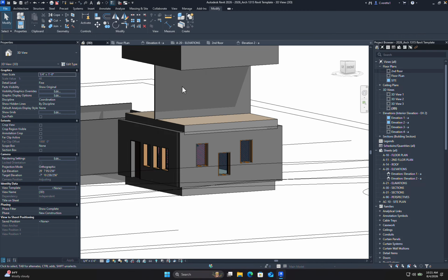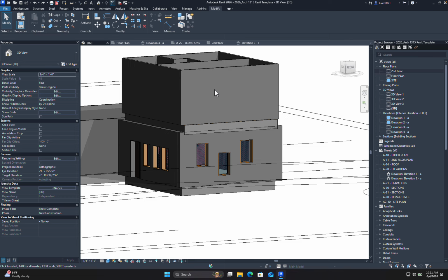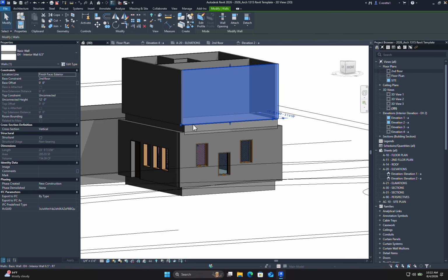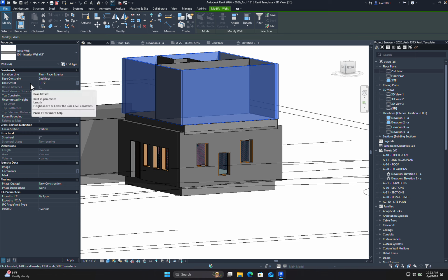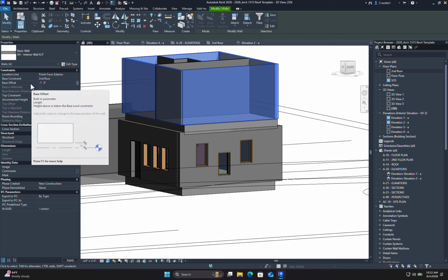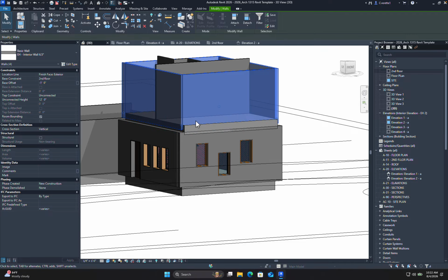It's not as intuitive as like typing move and being able to move stuff. I can't no longer do that, right, especially in Revit. But I can control things with numbers. So for instance, if I took all those walls again, and I did say a skirt of a negative 12 inches, it's going to bring that down because it's essentially controlling the base. You guys saw that? It kind of moved the whole thing down though, right? So I may still want a top constraint.